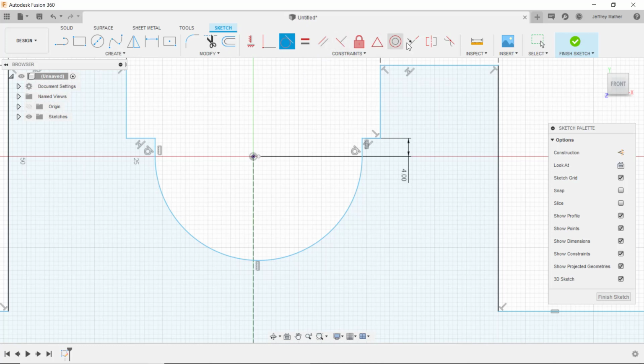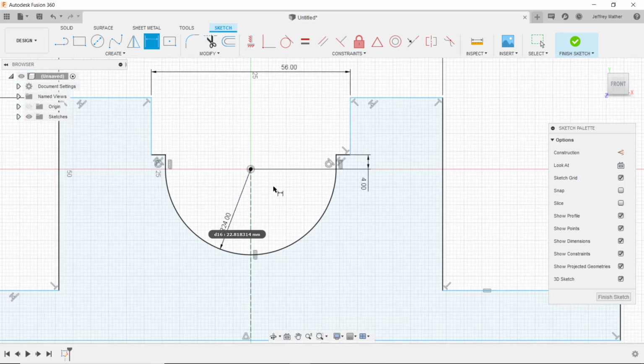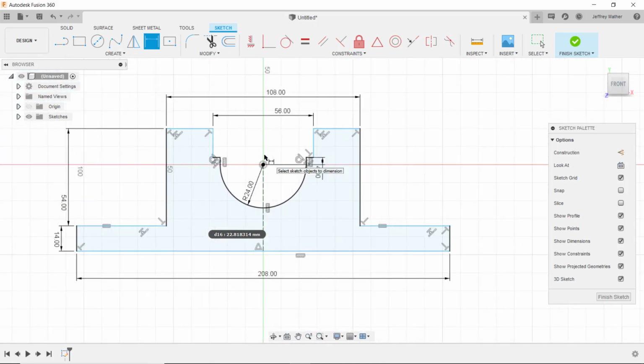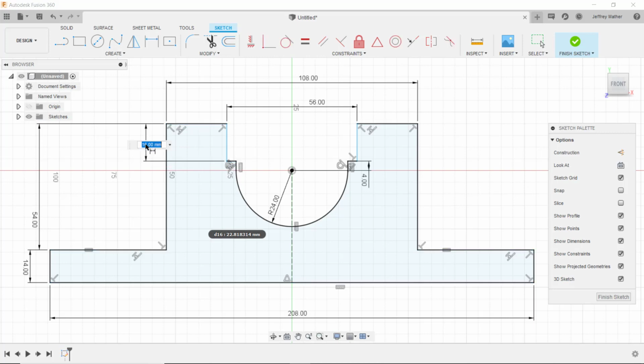And so let's do this again. I'll do coincident, put this back at the origin, put the dimension back in there. I somehow lost that during my trimming. It turned black again. And then I lost the 16 when I did a trimming. So this is where if you do one line at a time and constrain it, you won't run into this situation where we have to go back and fix things.